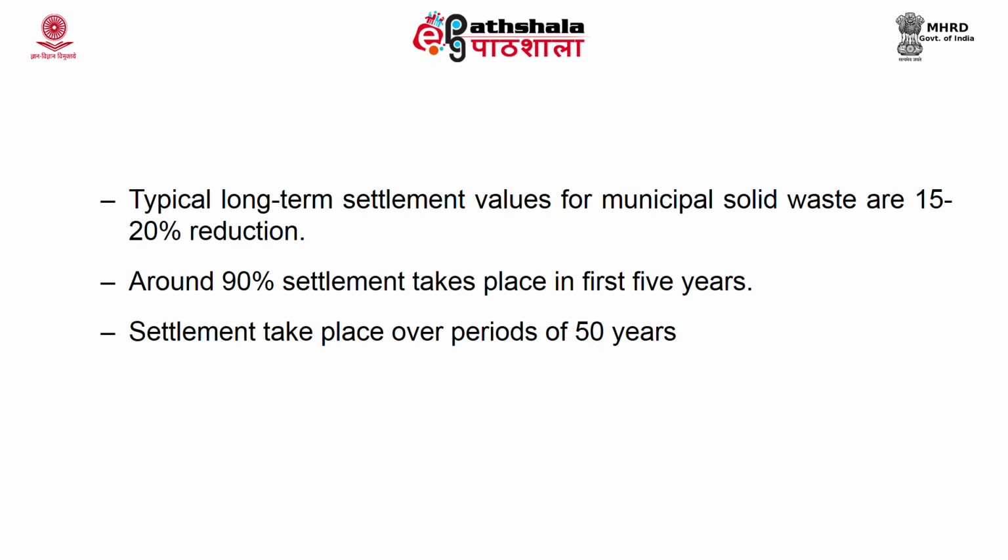Now, the settlement takes place gradually and it goes up to 50 years, that is the entire design period. The inert waste shows very low settlement because their density is high, as well as they do not degrade, they are inert material. So, they show very low settlement.